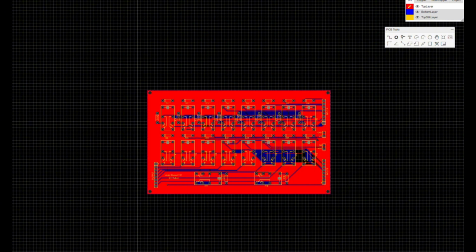ANDs basically work by you put the power through to this one, which turns this one, and this one, which changes through and puts out. An OR is using these 2 relays as well, while a NOT uses this relay here, and it basically is on the always closed. If you power it up, it goes to always open, or normally open, should I say, and that breaks the power, which turns off the output. With a NOT though, it has to only be the A, because these ones are not hooked up to anything, so when you put values in here it just does weird stuff, so you just don't do that.